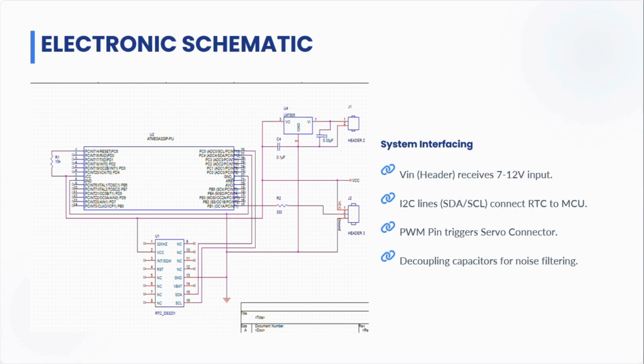When the time matches the user's feeding schedule, the microcontroller sends a signal out through a dedicated PWM pin. This pin triggers the servo connector, which will physically open the feeding gate. Additionally, you will notice decoupling capacitors in our interfacing strategy. These are crucial for noise filtering, ensuring that electrical interference from the motor does not disrupt the microcontroller's logic.